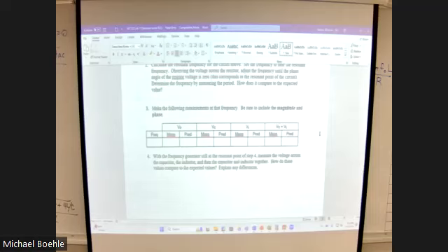The fact that you got about half a volt across it, lost half a volt out of 5, would indicate that it is somewhere close to roughly 1/10 to 1/11 of what the resistor value was. That was a 1K resistor, so you're talking about 100 ohms of resistance. Realistic. That's what you're going to have. Right?